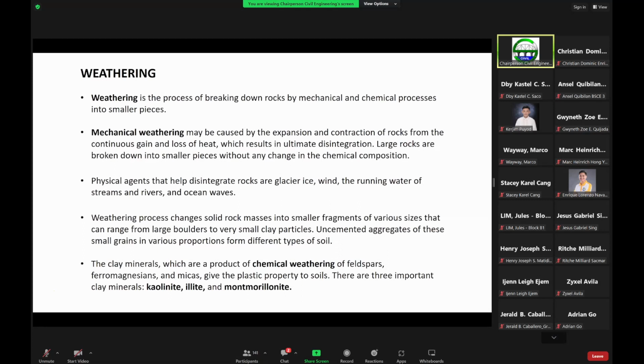I think the most problematic of these is the montmorillonite clay mineral, because it usually gives the expansive nature of clays, which we don't want in practice. Normally if we have expansive clays, I recommend to remove and replace.